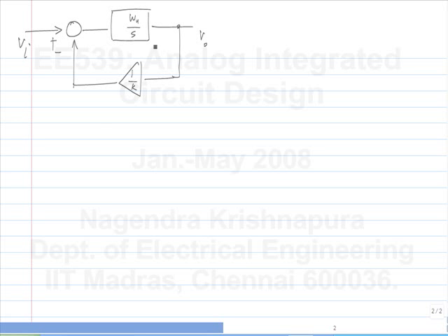So the feedback part, in case of an amplifier, consists of just an attenuator, and we assume that we can realize it using passive components. Okay. Now this part is realized using an op-amp. Okay, the op-amp is designed to realize this part. So it takes the difference between two inputs, and also it has a frequency response that is more or less like that of an integrator.